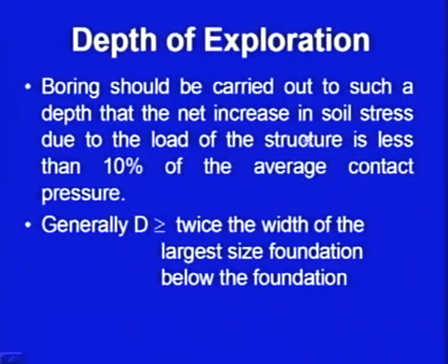As a rule, the boring should be carried out to such a depth that the net increase in soil stress due to the load of the structure is less than 10% of the average contact pressure. We use this statement as a thumb rule. What it means is that there is, let us say, some contact pressure, and as you go deeper and deeper, the incremental pressure, the increase in pressure because of the foundation, goes on decreasing. So, roughly if you go up to that depth where the increment in pressure is of the order of 10%, we assume that that much depth is going to contribute towards the settlement of the structure.